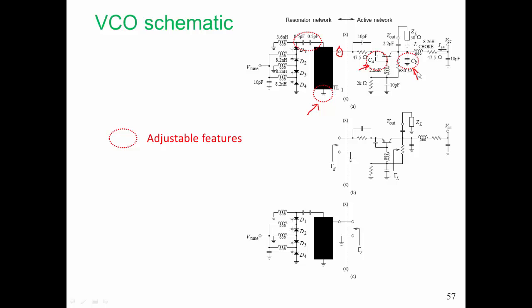Now, if we were designing a VCO over a fairly narrow tuning range, we would not have to worry about that. But going from 4.5 GHz to 5.5 GHz, that impedance changes significantly, so the feedback element in the Colpitts network changes quite considerably, and we need those capacitors to accommodate for that as well as all of the other parasitics.